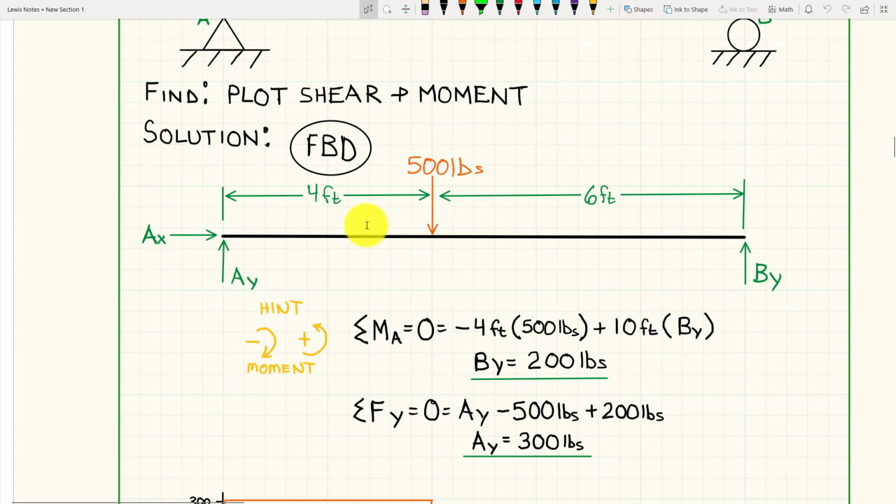So we need to put a negative on that. Now, the By is at 10 feet, and it's going up in a counterclockwise manner right here. So that is a positive moment. When we solve this, it's going to tell us if By is up or down, and our math says yes, it was correct. We always guess positive in our guesses for things like Ax, By on these. Just kind of a refresher from strengths class.